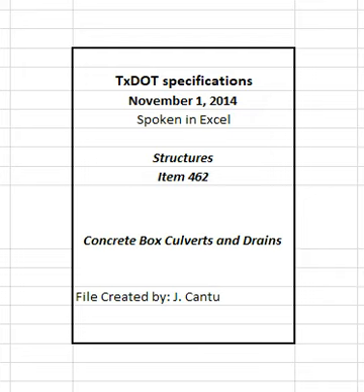Protection methods for excavations greater than 5 feet deep will be measured and paid for as required under Item 402, Trench Excavation Protection, or Item 403, Temporary Special Shoring. Excavation, shaping, bedding, and backfill will be paid for in accordance with Item 400, Excavation and Backfill for Structures. When jacking, boring, or tunneling is used at the contractor's option, payment will be made under this item. When jacking, boring, or tunneling is required, payment will be made under Item 476, Jacking, Boring, or Tunneling Pipe or Box.